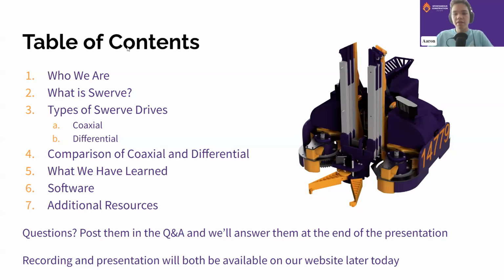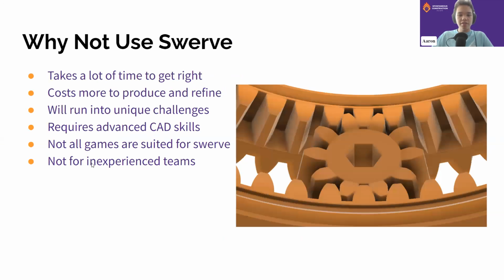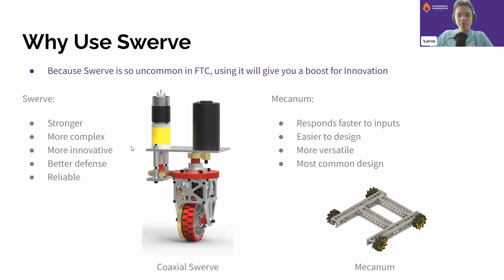There's also a question about using servos for a drivetrain, which I would like to reiterate on. They asked about CookieBots' method. I do believe CookieBots has a setup called coaxial swerve, which is the one that looks like this, where one motor turns the pod and one runs the pod. In their case, they have one DC motor that drives the wheel itself, and the turning of the pod is done by, I think you're right, a super speed servo.